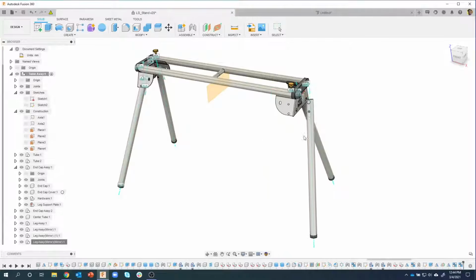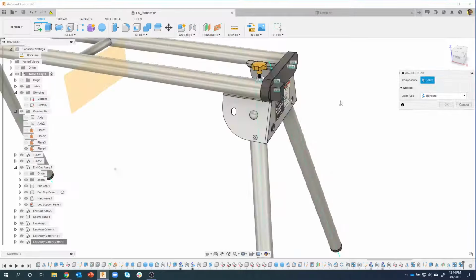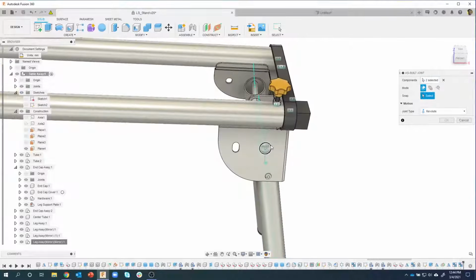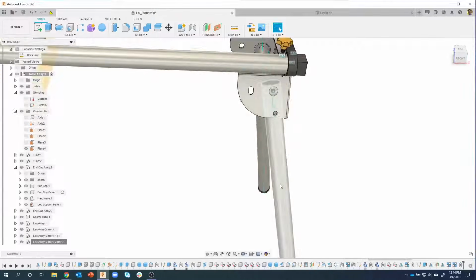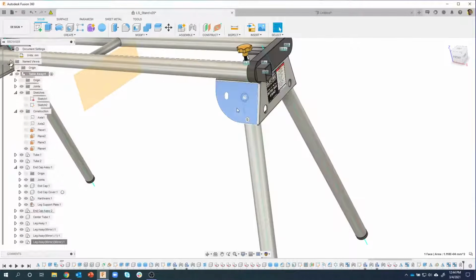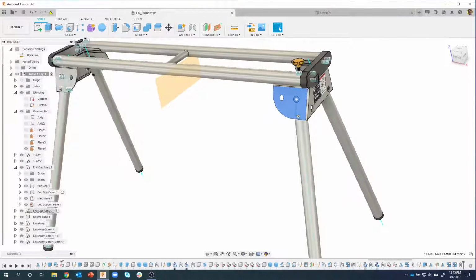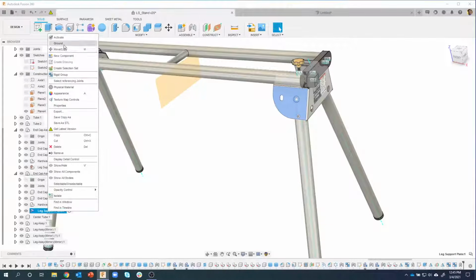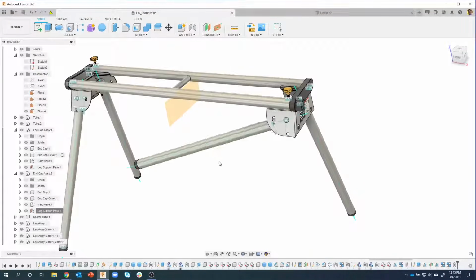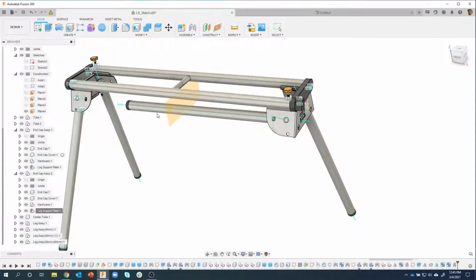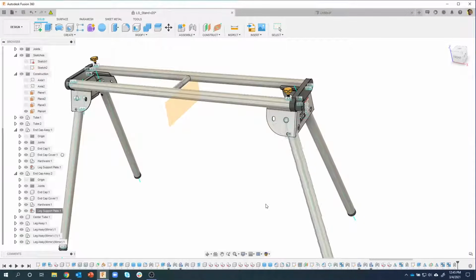Now I just need to create the as-built joint. So I'll just come in here and say as-built joint, that. I want to do a revolute around maybe that bolt right there. I'll say OK. And we now have, oops, I need to ground that guy too. So let's pick on him. That is part of the end cap assembly 2. Let's ground that guy. Now if I grab that leg, we can sure enough test to see how that would rotate into location. Pretty cool.